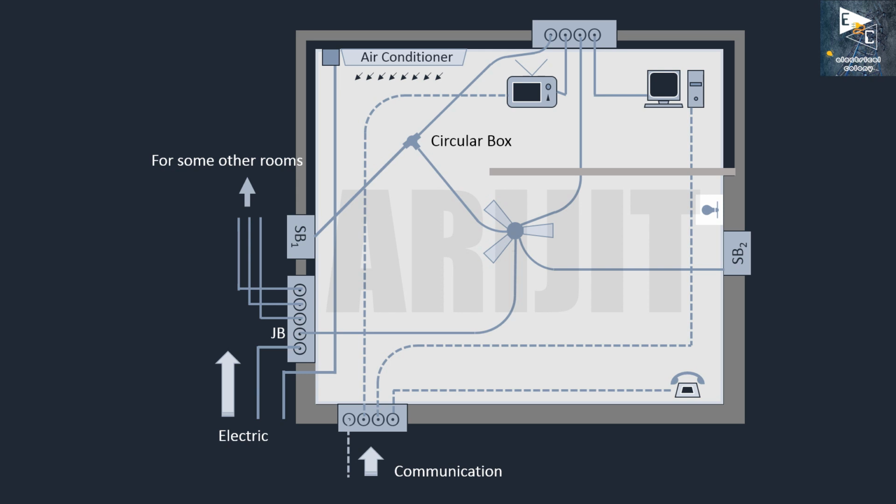And from here starts the problem, where you need to be very cautious while boring the holes in the wooden cage, because from an electrical drawing you cannot configure the active phase of that boundary, and unless you get confirmation about it, you cannot start measuring for placing circular and fan boxes, which means you need to follow the civil drawing and electrical drawing simultaneously.